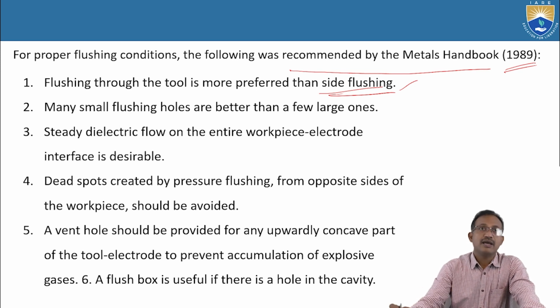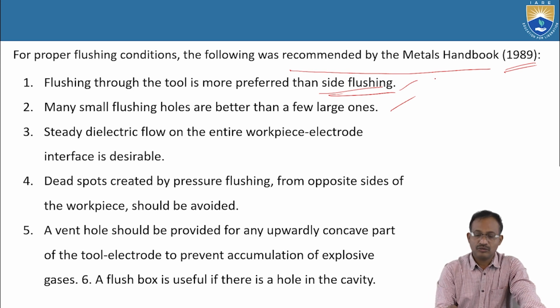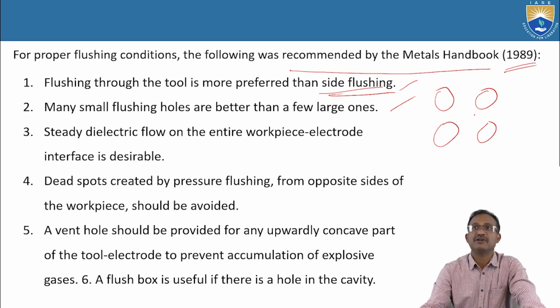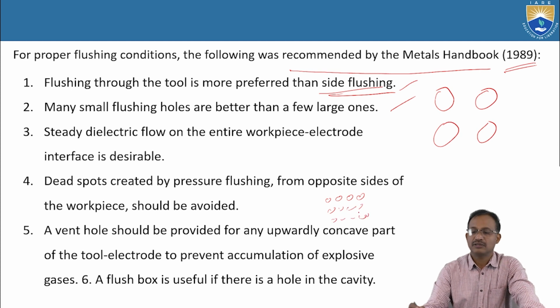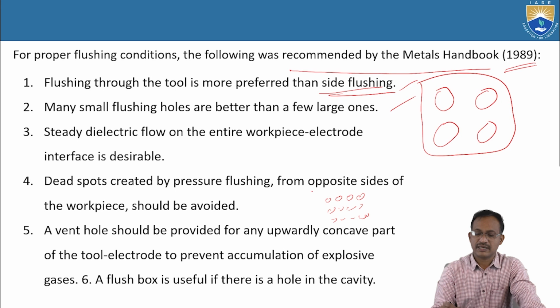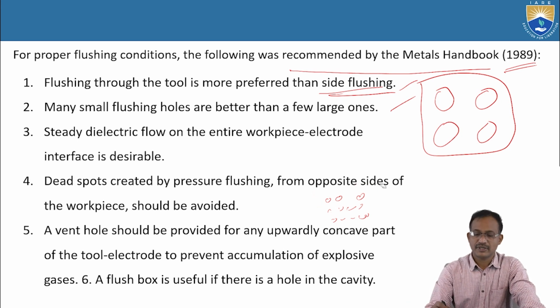Second one, many small flushing holes are better than a few large ones. So instead of having large holes for flushing, we better provide small holes, considering the same area.